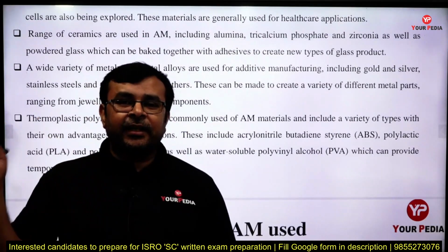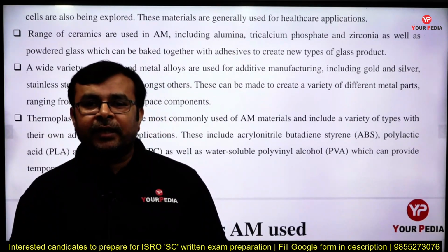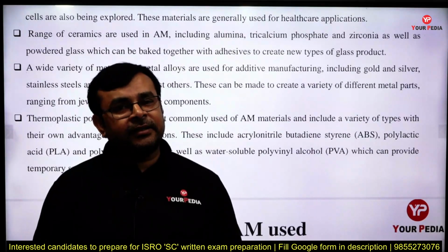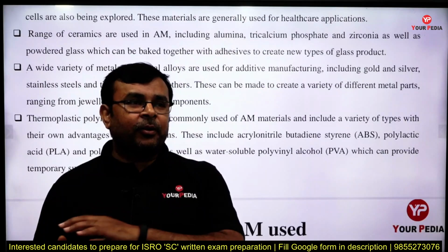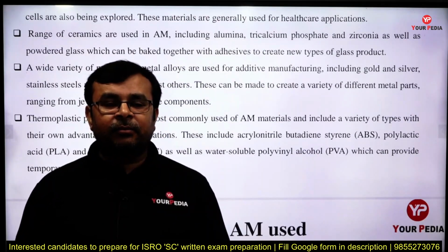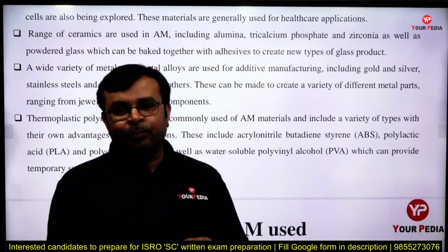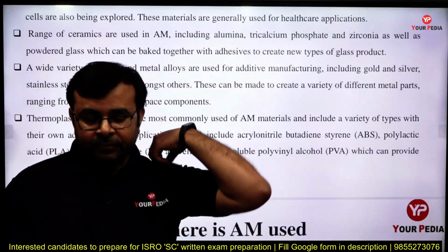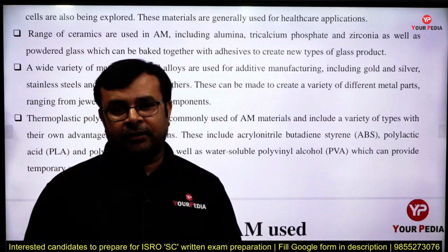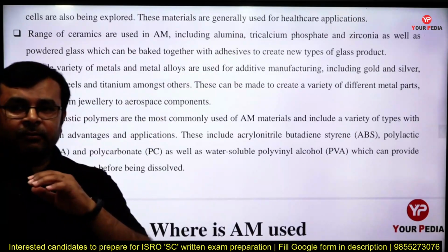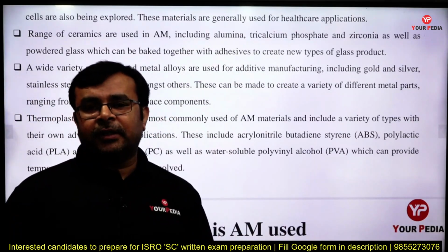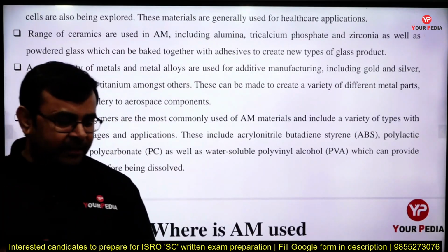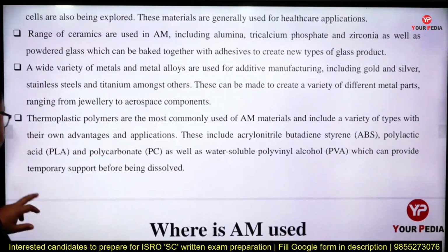When it is heated, it gets soft, and after cooling it gets harder, and after gaining its hardness, it is not possible to heat it again and make it softer. Why? Because mostly thermosettings are made by a condensation polymerization process, while thermoplastics are mainly produced by an addition polymerization process, correct.